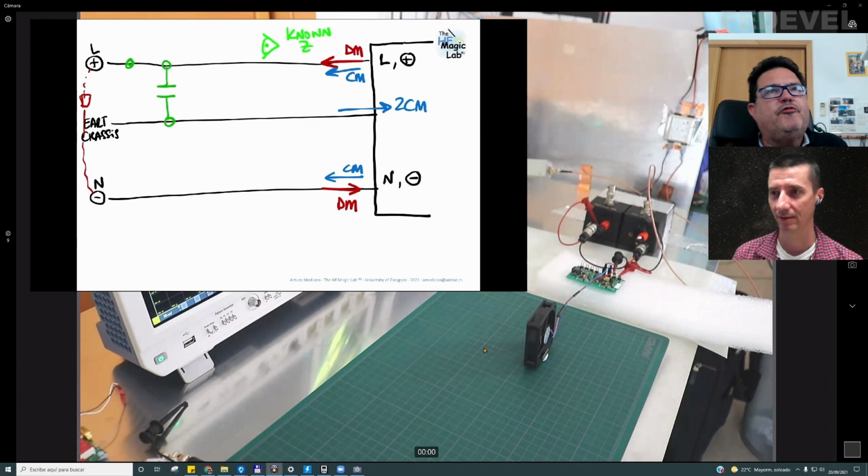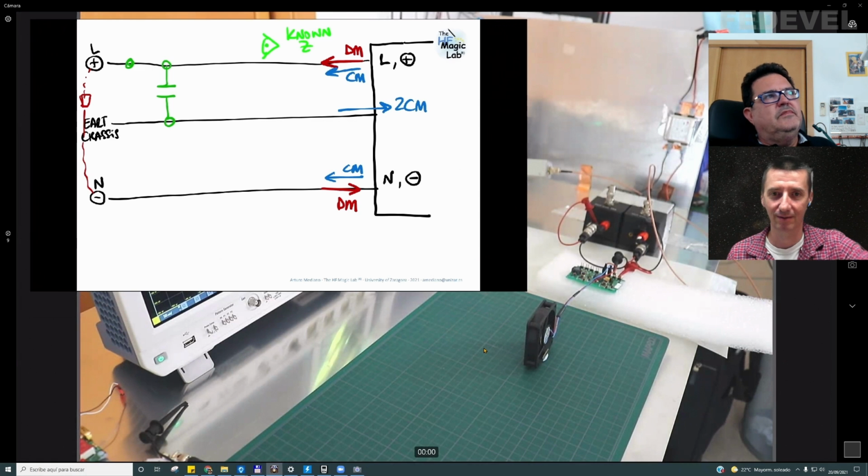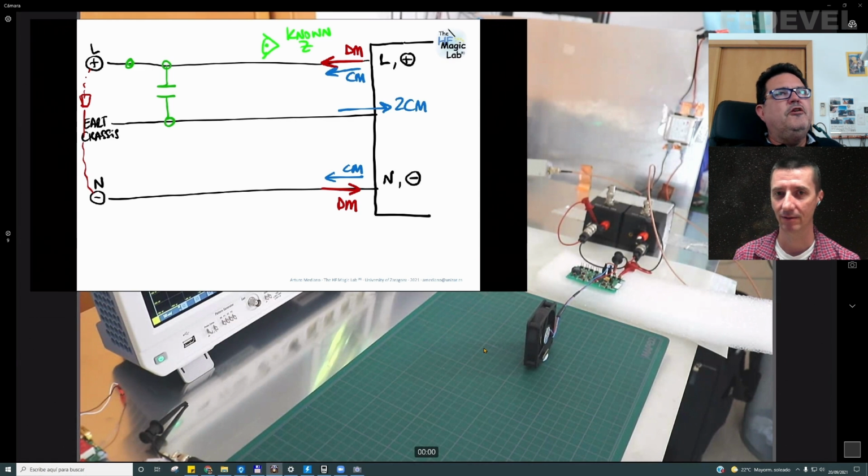This is typical, for example, of products on the mains network that are called class 2 circuits with double insulation. They don't have a ground connection, and many other applications. But in a real application, this noise will theoretically be coming out from your board anyway, because everything will be coupled to ground. In radio frequency, there is no concept of disconnection. In radio frequency, you always have things connected through these kinds of parasitic capacitances.